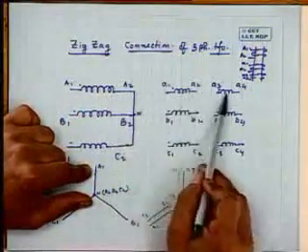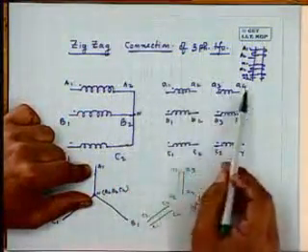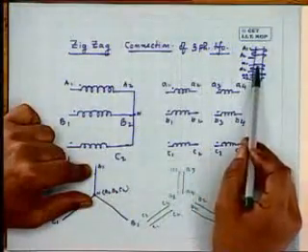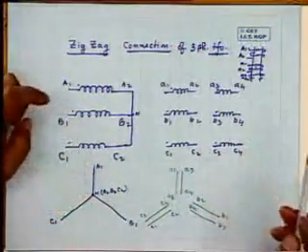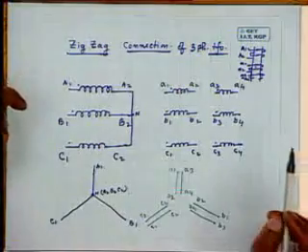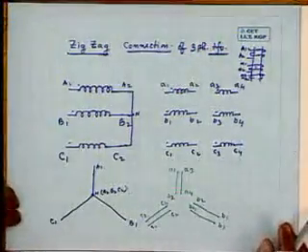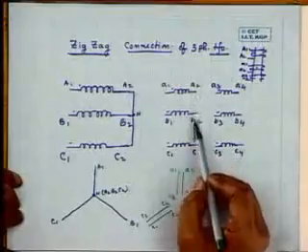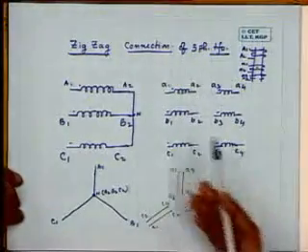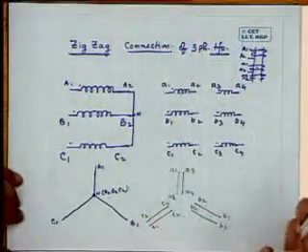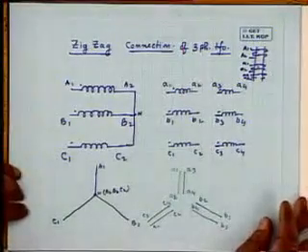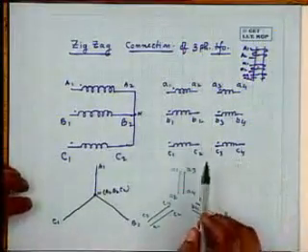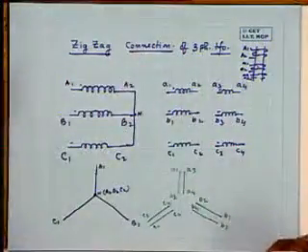These voltages are just available the moment you energize, because A phase voltage is this. It is on the same limb. So these voltages will be in same time phase. Getting? That is, if you short simply A2, B2, C2, you will get that YY0 connection. Suppose you forget about others.